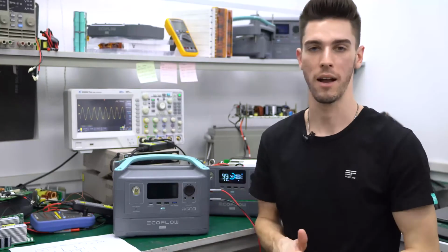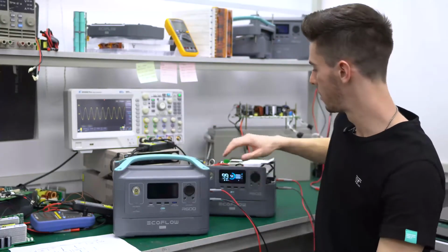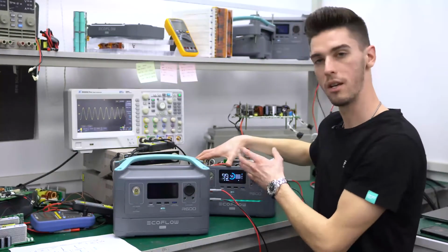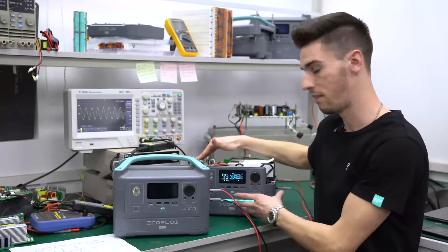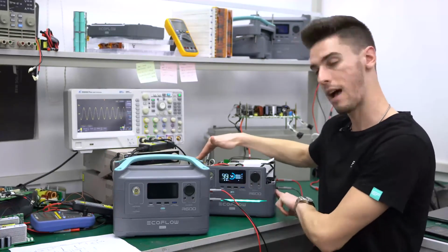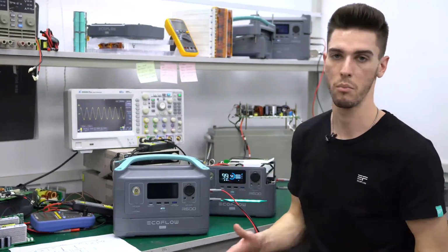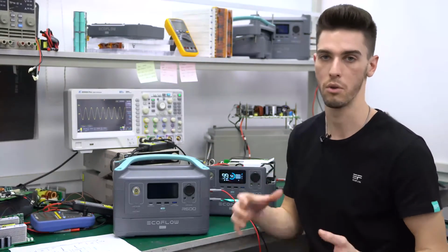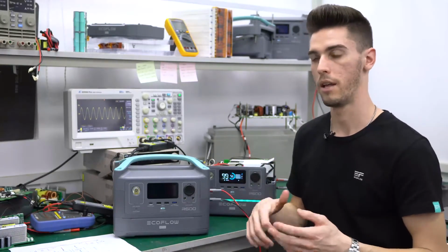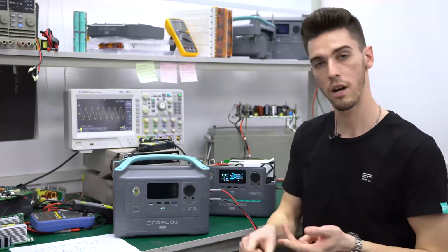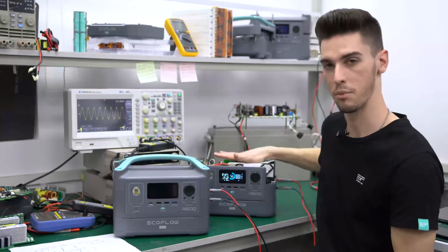All right, so I just wanted to circle back around and highlight a couple things I mentioned about the extreme bypass safety feature and the UPS function. So for the extreme bypass, the reason the overload protection system gets triggered is because the AC input only has a 900 watt max, and there's a 300 watt reserve for the battery. And this output has a 600 watt max, so there's only a usable 600 watts. The great thing is most home appliances like TVs, personal computers, lights will fall below this power demand. But if you need to use something that has a higher power demand, like a hairdryer, coffee machine, anything with a heating element, you can simply unplug the AC input and leverage the X-Boost feature.